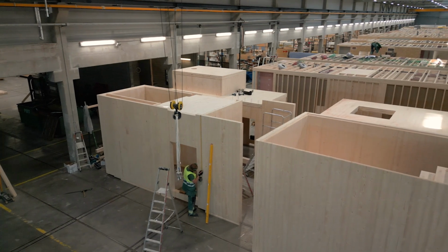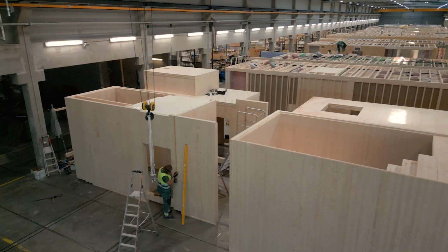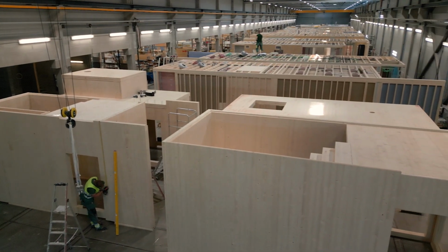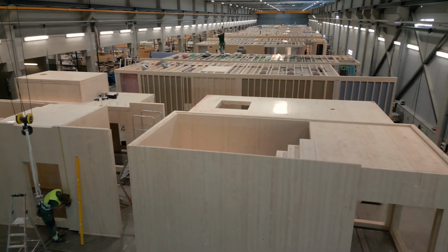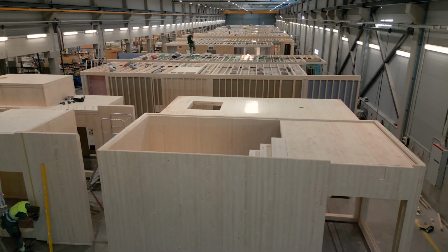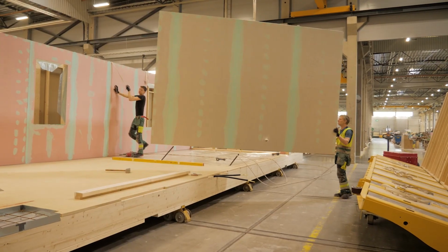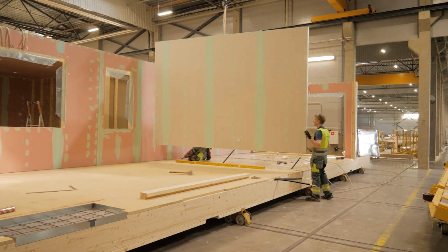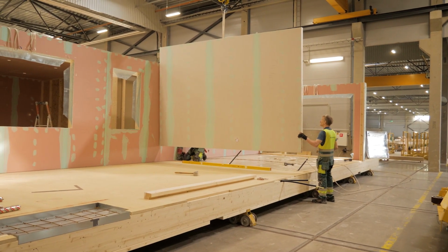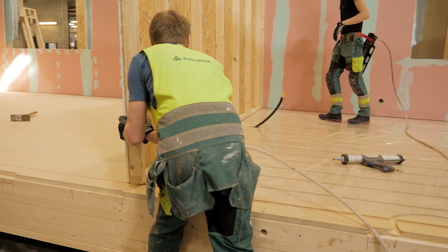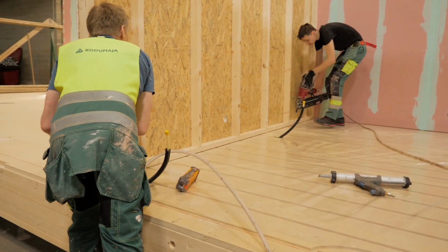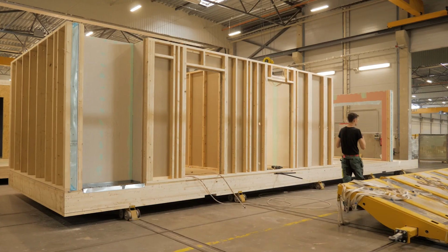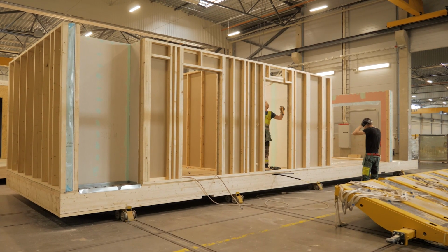In house factories that produce volumetric elements, separate production areas, or dedicated production halls, are established for these volumetric elements, in addition to the production area designated for planar elements. Compilation of the volumetric element begins with the erection. This takes place in the corresponding erection area, where the floor panel, wall panels, and ceiling panel are assembled. After the panels are assembled together, they form one complete volumetric element.